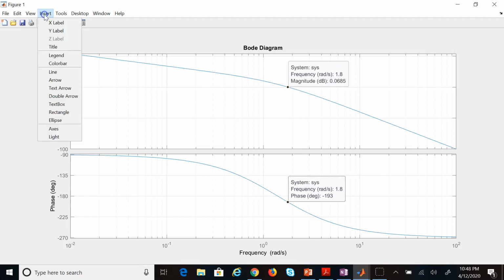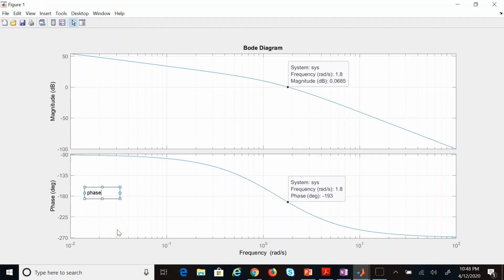And you see it's negative 193. So how much is the phase margin of the system here? If you remember, the phase margin is this angle, whatever it is that you found, plus 180, right? Which is going to be negative 13 degrees. What does it mean? You remember, negative phase margin means the system G1 is unstable, right? We need both positive gain and phase margin to be stable. This system has negative phase margin.